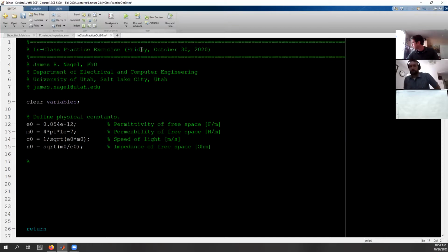So, Corey made the comment a long time ago that the Smith chart is kind of like an analog computer, and that is very, very true. But sometimes in this context, it just helps to think about these matching problems in terms of the Smith chart as a visual aid that follows very simple geometric rules that are totally in contrast from the actual algebraic expression. So I want to do this parallel approach where we'll do the math, but then we're going to visualize each step along the way using a Smith chart plot, okay? So let's go ahead and get into that.